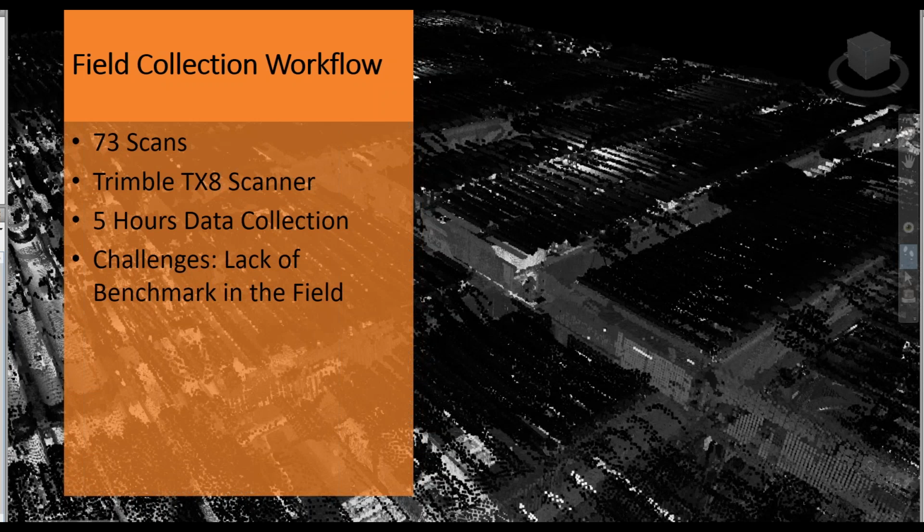We are running a Trimble TX8 scanner. Our Southeast region is one of the only ones in DPR running the Trimble scanner. A lot of our guys are running Faro. And I know some of those guys are using Verity as well, so the program's a little agnostic when it comes to scanner types. Took about 5 hours. I think I started at noon and finished around 5 p.m. taking the data.